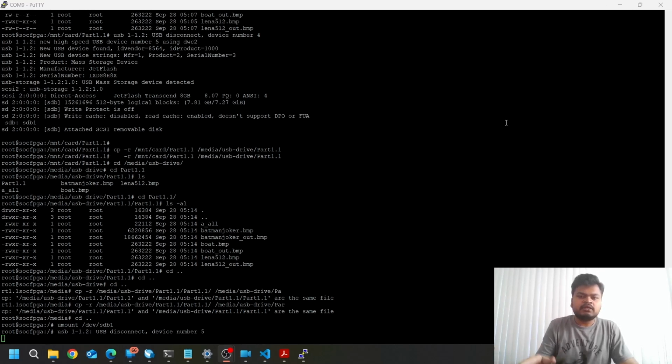In the FPGA there is Verilog code, one to avoid the noise and the second one to detect the edges of the images, as the Sobel filter does in the HPS. Once it has been executed, it will send the output image to the HPS, then the HPS writes the image out, and then we can see it in the file.